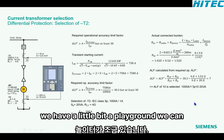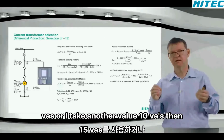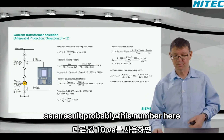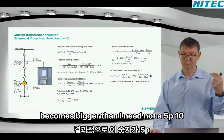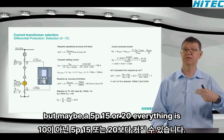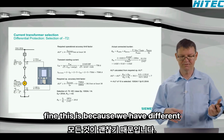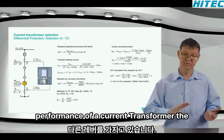Now you see there we have a little bit of a playground. We can also say, no, I don't want to use the 20 VA. I take 15 VA, or I take another value, 10 VA. Then as a result, probably this number here becomes bigger. Then I need not a 5P10, but maybe a 5P15 or 20. Everything is fine. This is because we have different levers for defining the performance of a current transformer.